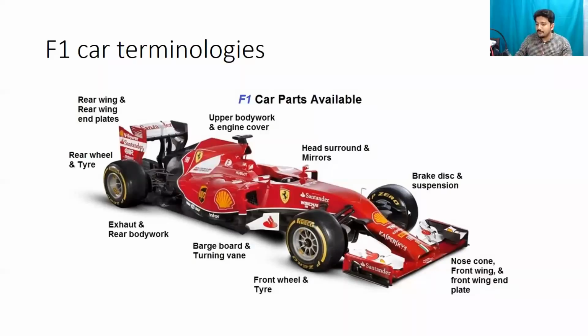So the front wing is used to generate downforce. Yes, that's correct. What else is it used for? There is another reason for using the front wing, and especially with the end plate on it, there is a particular reason why the end plate is on there. It helps in pushing the air upwards to increase the downforce. Parth, that's exactly the same answer as Jennifer. So what other reasons, especially the end plate? What else can I use it for?